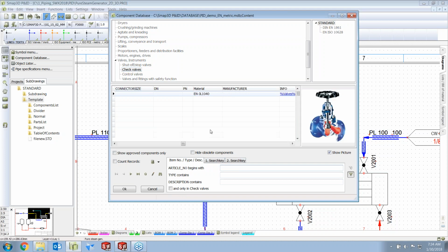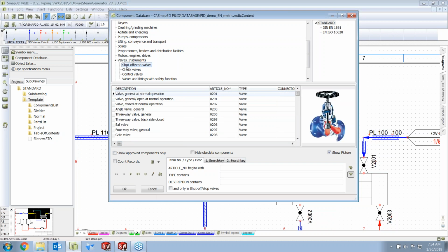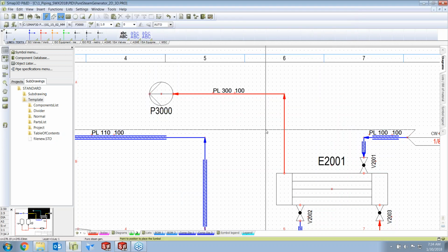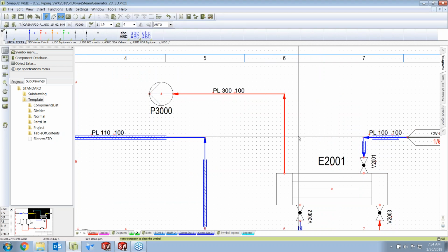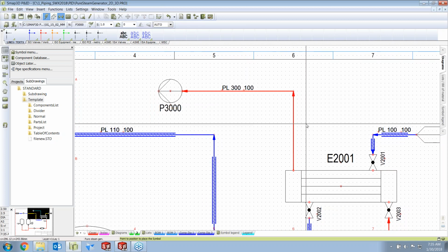get everything, and anything that we go in here and basically with this, we could put any valve that we want into this pipeline, and any size valve that we want into this pipeline. And that could be error prone if we put the wrong thing in there. So we don't want to put a low pressure rated valve into a high pressure pipeline. Okay, that's the way that you either cost a lot of money or potentially get somebody hurt or killed.